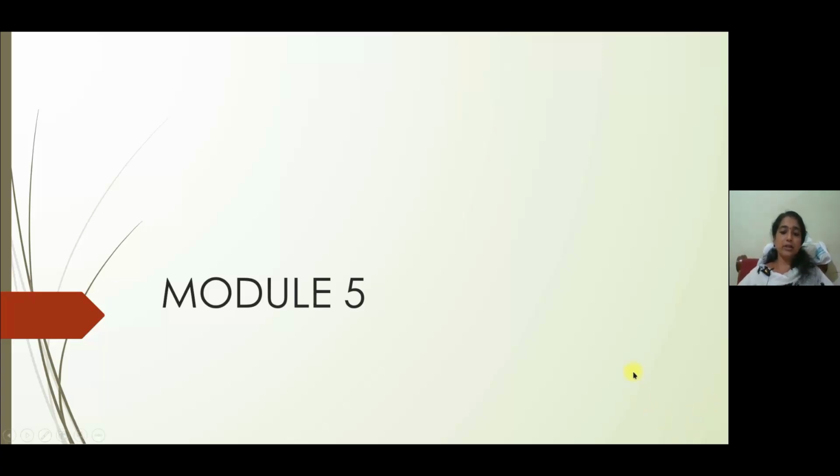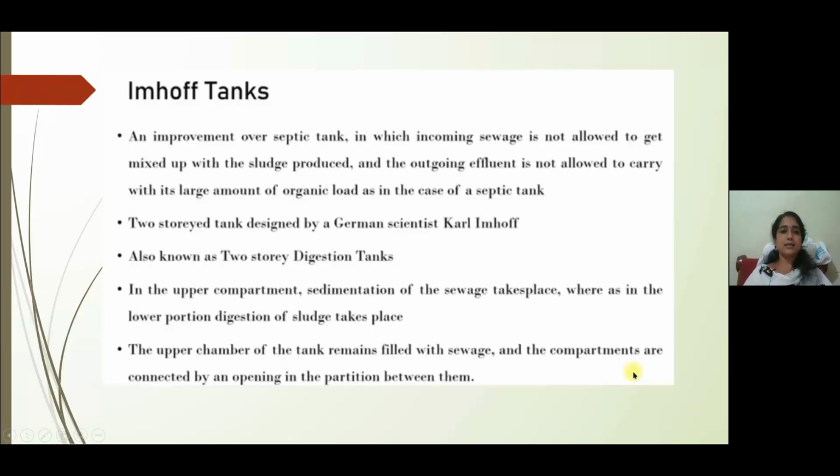In this session, I am going to discuss the Imhoff tank, which is an improved version of the septic tank in which the incoming fresh sewage is not allowed to mix with the sludge produced in the tank, and the outgoing effluent is not allowed to carry a large amount of organic solids as in the case of a septic tank.